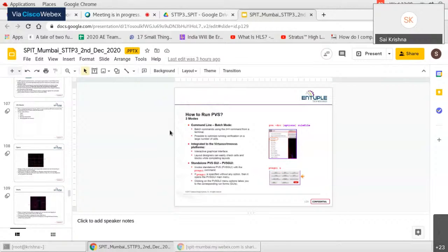Using all four of these, we proceed to physical design, where you first start with floorplan. You'll check aspect ratio and utilization. If you have macros, you will go for core utilization. If not, you will go for standard cell utilization. And yes, even the boundary spacing between core and IO.